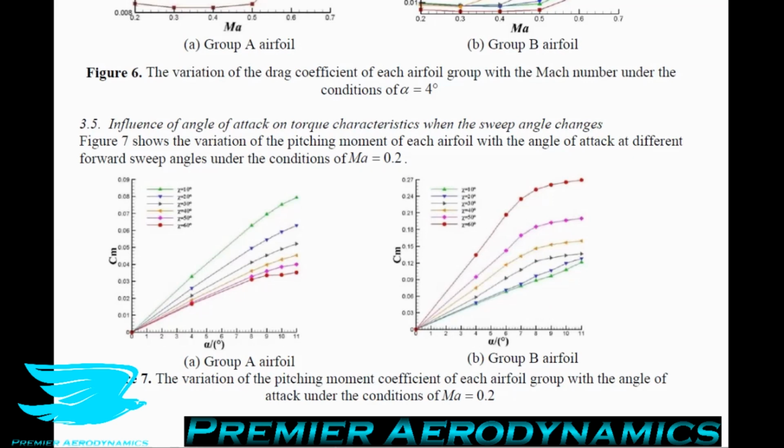For an aircraft, you want to have a negative pitching moment because you want the airfoil to be inherently stable. Let's say you're flying around at an angle of attack of 5 degrees. If you have a positive pitching moment, it means that the airplane wants to naturally pitch up more, so nose up. If that happens, you start increasing the angle of attack, which means you increase lift even more, and that will generally increase the pitching moment even more. Then you get this cycle happening to the point where you get to an angle of attack so high that you start stalling. You lose lift, and that's bad. You then fall out of the sky.